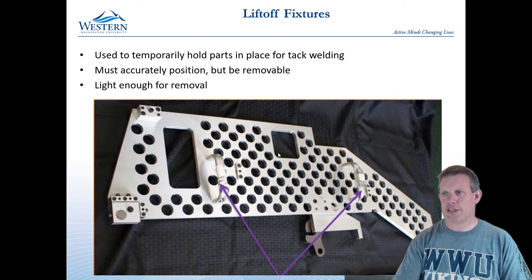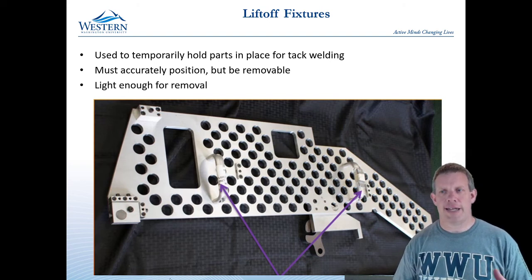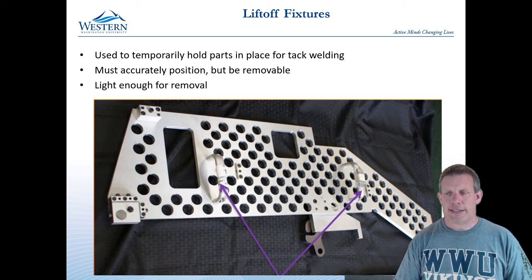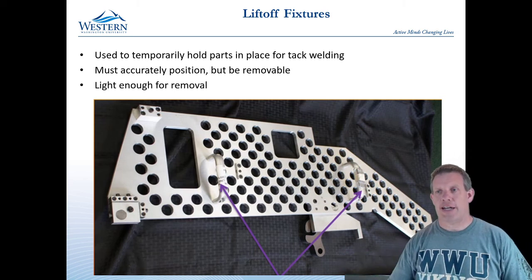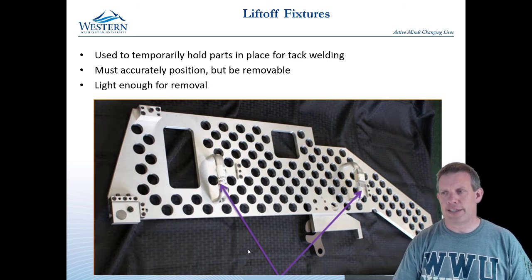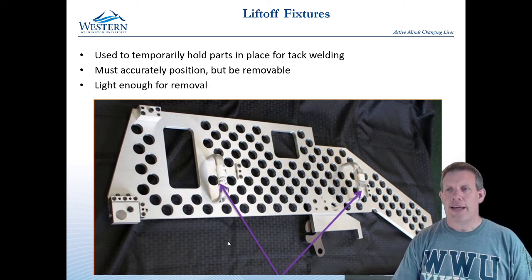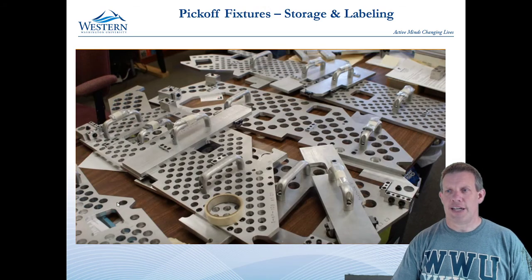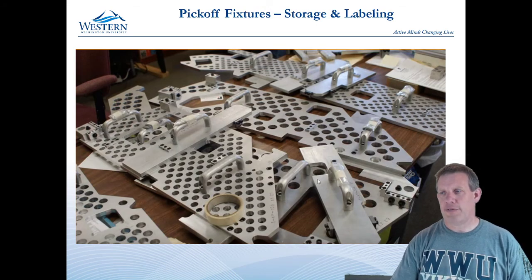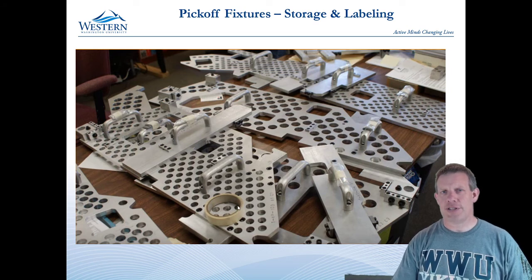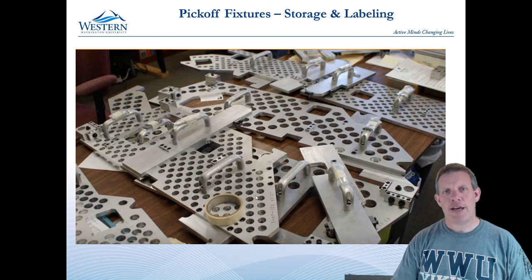Maybe it happens around the edges, maybe it happens in these windows, but it has the access, but at the same time it really just clamps the entire part, has a bunch of lightning holes drilled in it so that it will be lighter and easier to deal with. And you can see that this company uses a ton of them, and they have them worked out so that they can stack on this table somewhat effectively. Now the handles that they have make them install very quickly but make them not stack very well. Anyway, so they have some cutouts to be able to do that. Just a way of dealing with welding fixtures that are kind of big and bulky.